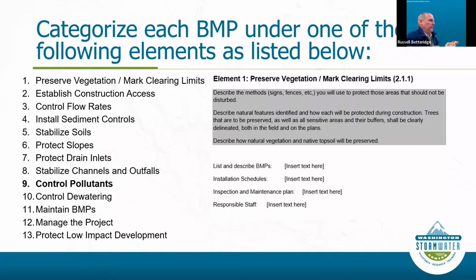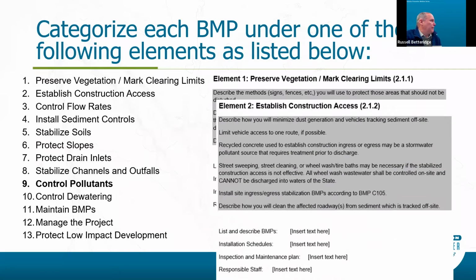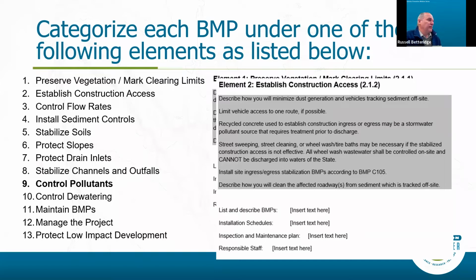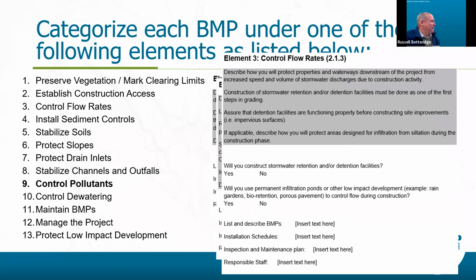Then I start to say, well, list that BMP down. And Royce is going to talk more about how to do that. You know, establish your construction access. You may have several different access points at several different times, that phasing of your project. Maybe sometimes the big trucks have to use one entrance and the small trucks have to use a different one. Make sure you anticipate what's going on your project when it comes to that construction access. Make sure it's written in your plan, you know, when and how and where. Train the people so that they know that BMP C105 is going to be active during these times and all other times.